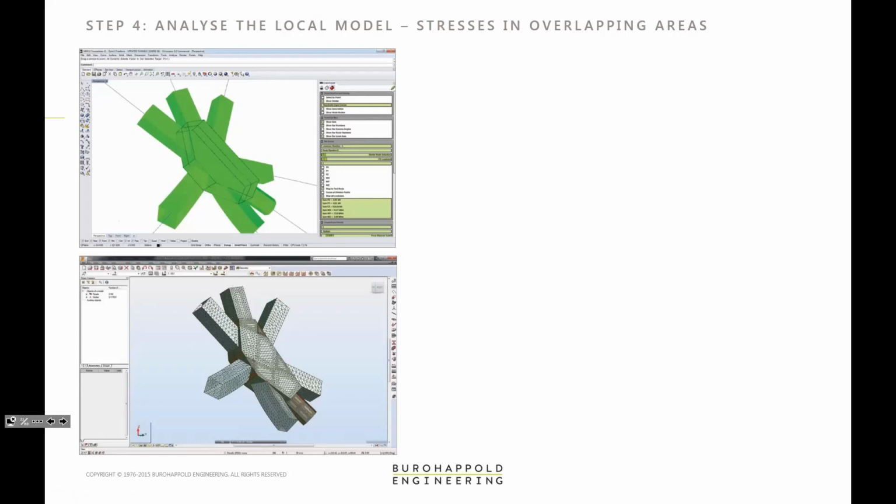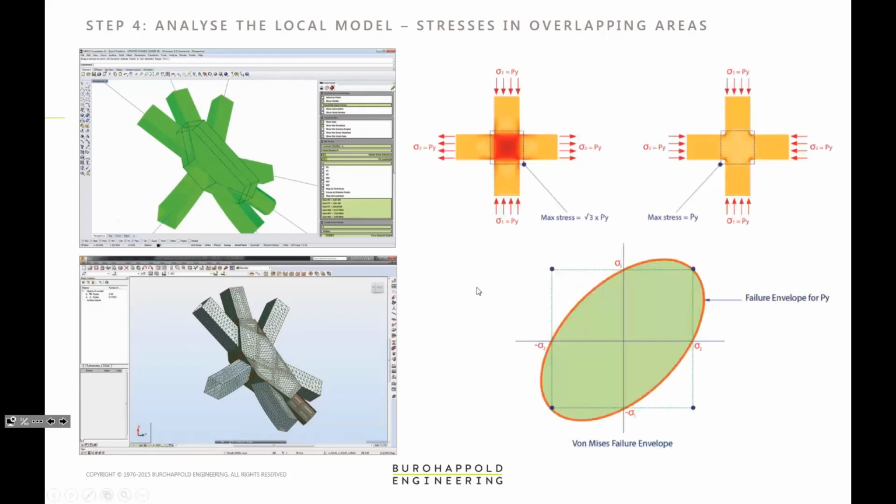When they start interacting, you can't have a 50 thick plate, you're going to need more. And you can do a little test yourself. This is Poisson's ratio effect. So if you compress something, it's going to bulge. It's already going to have tensile stresses in an orthogonal direction. So if you pull it in that direction as well, you're going to get over yield very, very quickly.